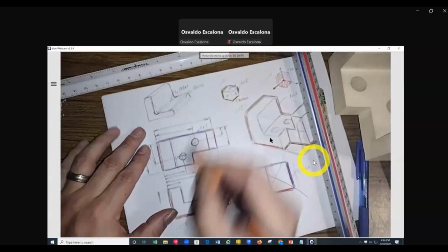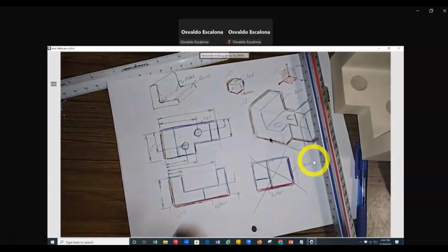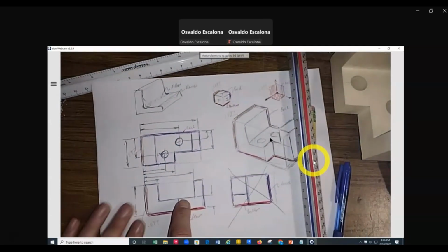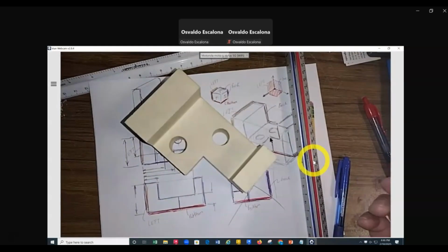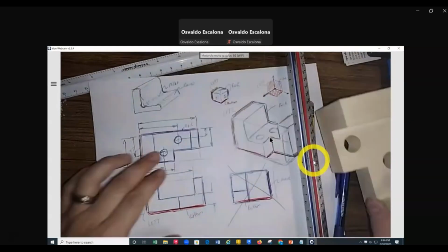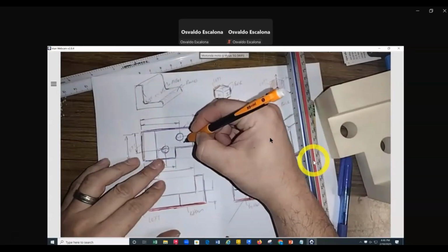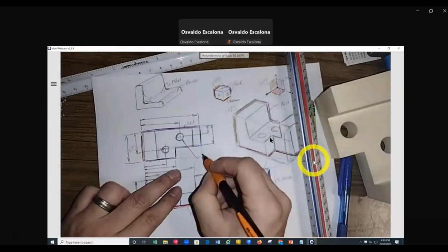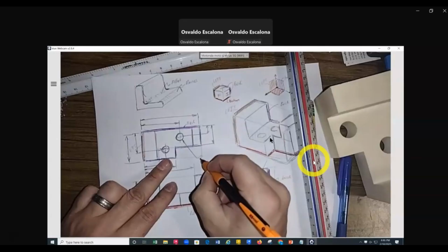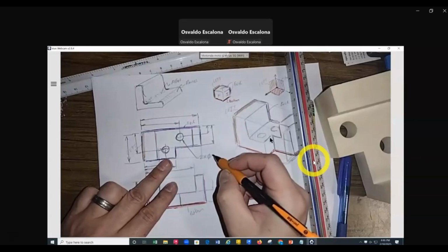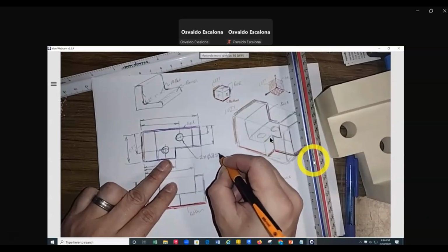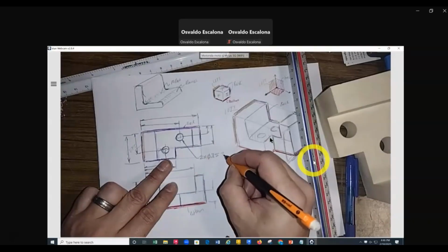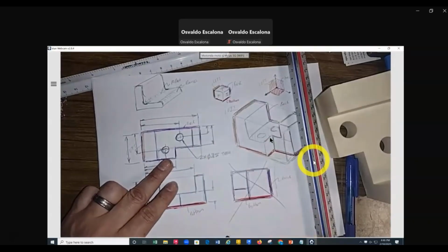Question, do I have fillets? No. Straight, right? No fillet. Any rounds? No rounds. Any holes? Check. I have to call them out. So go towards the center of the part, move away, boom, boom. I got two of them, so 2 times diameter. The size of the hole, let's call it 0.75. Both of them I go through, boom. Does that make sense? Okay.